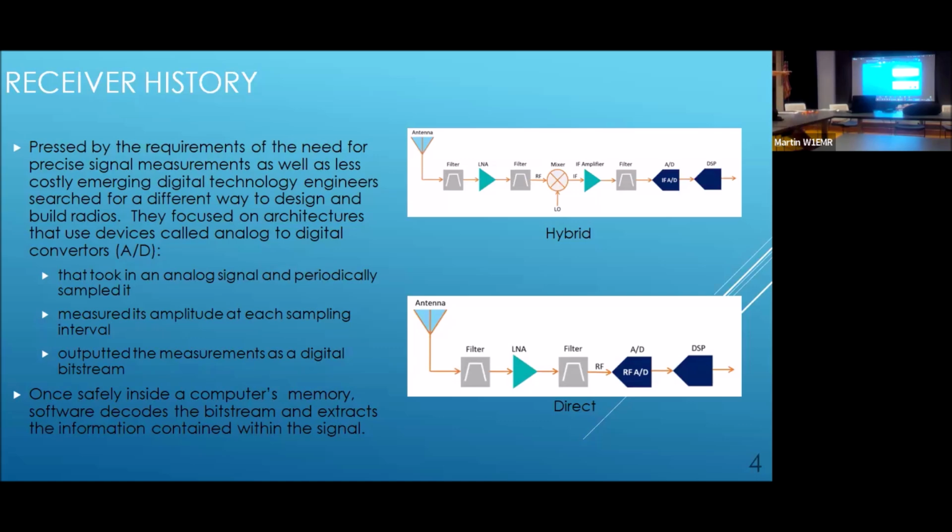So the A to D converter is actually looking at the RF spectrum as picked up by your antenna and sampling that directly. And that works great. And it gets rid of a lot of problems, but the A to D is a lot more expensive because it has to sample a lot more quickly. So that's the trade-off. What happens, though, is it's all digital technology at that point. So the device is getting cheaper and cheaper as they figure out how to put more and more of this stuff on the chip. So this has the potential for a lot of cost cutting. Superheterodyne receivers are not especially popular because you can't put all that stuff on the chip. And when you can't put all the stuff on the chip, the price goes up.